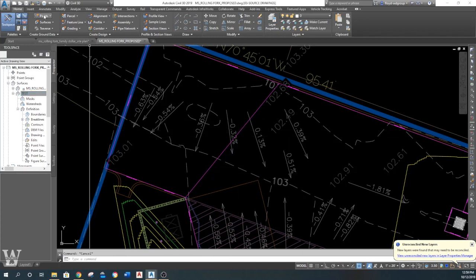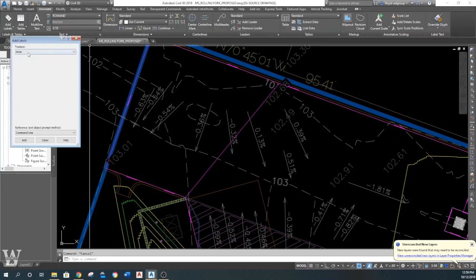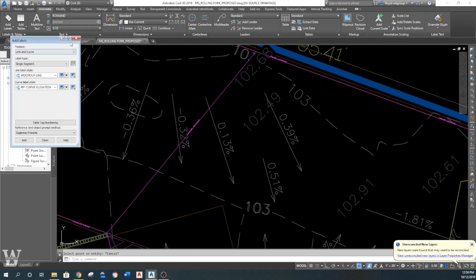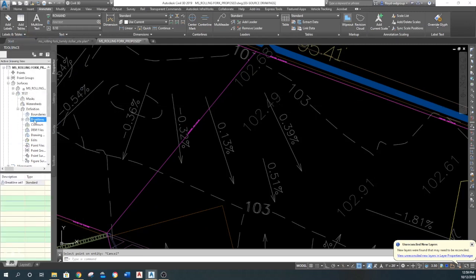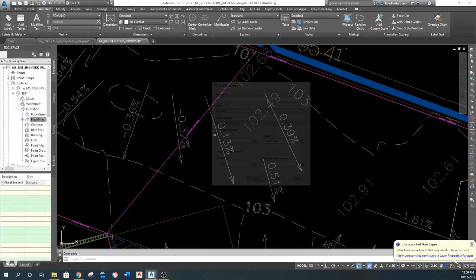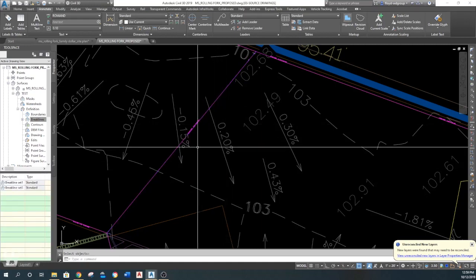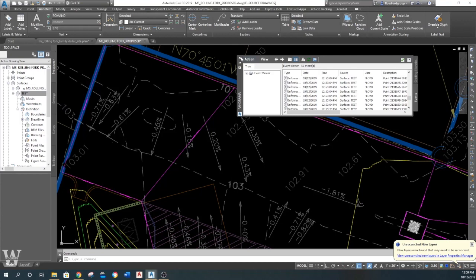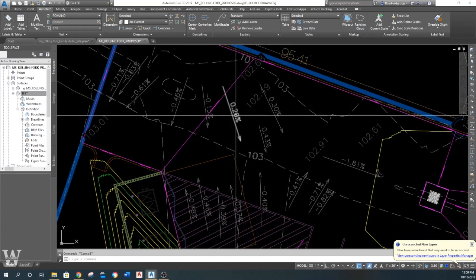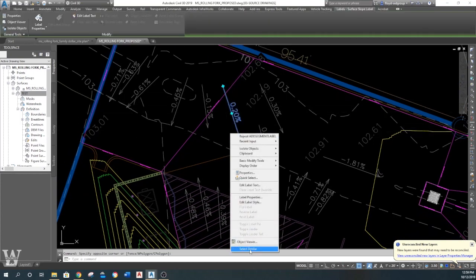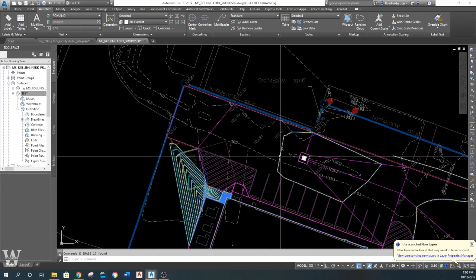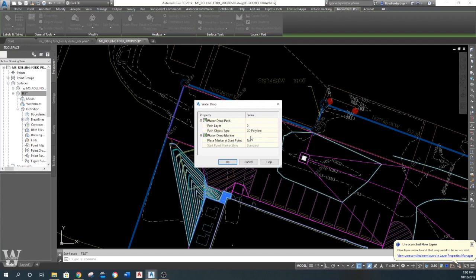Alright, and then let's annotate, add line. Let's do lines. Let's see what that elevation is. It's 0.25. So now we're going to go back here, break lines. We're going to add that line back, and we're going to regen, rebuild our surface. Okay. And so we're going to erase all these because our surface might be draining different with our water drops.